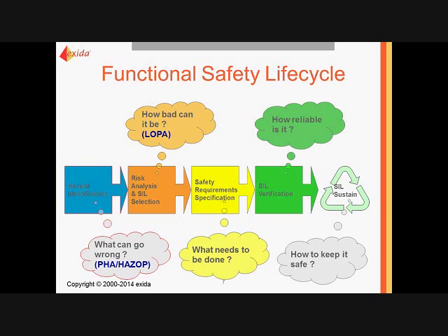And then you get into your normal operation life cycle of the plant and the safety instrumented system. And therefore what you do is you go through your management of change and your mechanical integrity programs. And if you make changes, if you have to replace equipment, what you should do is go back and verify that the equipment you're putting in is not going to have a negative impact on the safety instrumented function and will not change its safety integrity level.